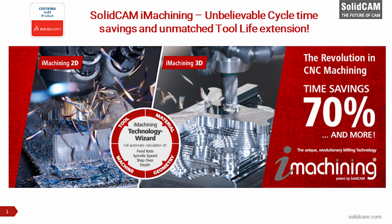And we're able to more effectively clear out areas of roughing than we would otherwise be able to do with standard or traditional turning operations. Also taking advantage of newer insert geometries and things like that that capitalize on some of the science of chip thinning.